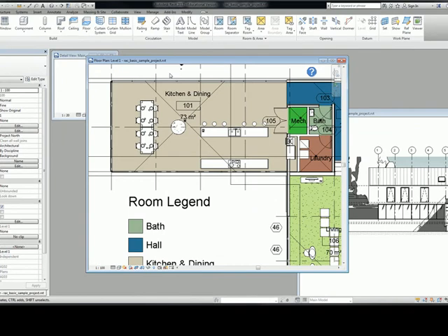And believe it or not, guys, these tags are also families. They have parameters. Those parameters come in the form of labels and geometry. So everything is just parameters and families the whole way through. Revit also has its own library of families. You don't have to go download. Yeah, the standard Revit families are pretty good and fairly expansive. What I find is, generally speaking, they're very generic, and sometimes you have to update them for code reasons.